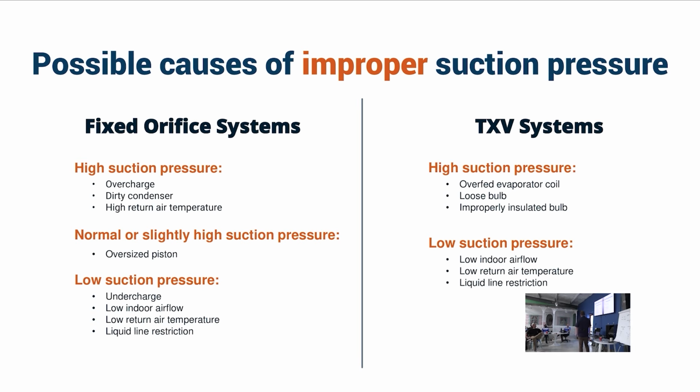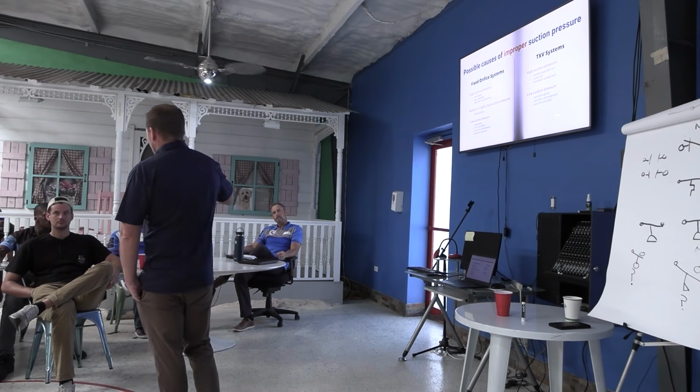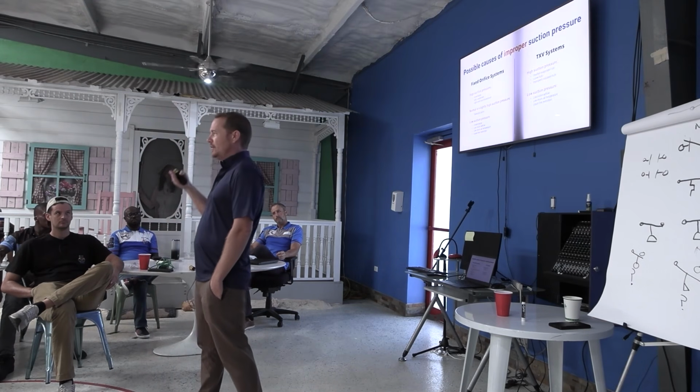But there's all these possible causes, and don't just assume that it's always one thing. Like guys, they'll start to get, it's low on charge. Suction pressure's low, it's low on charge, right? No, that's no. If there's one thing I can beat into your head, do not charge by suction pressure. That is not how you charge a system.